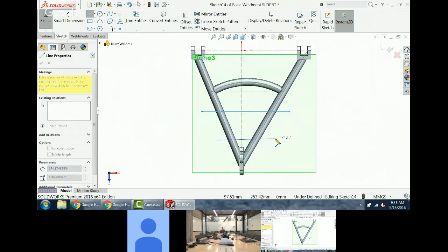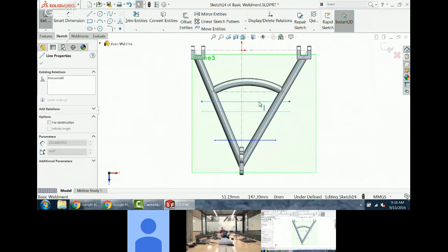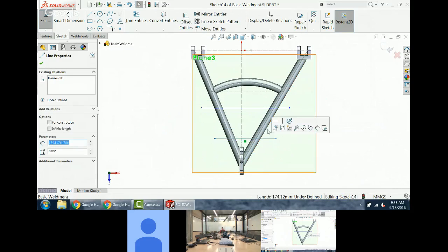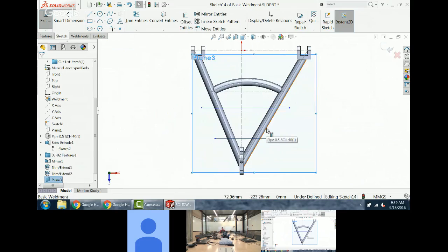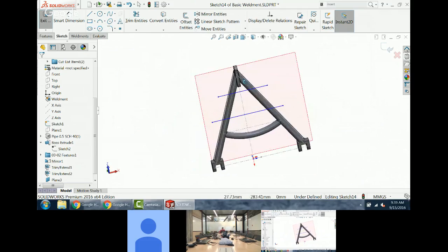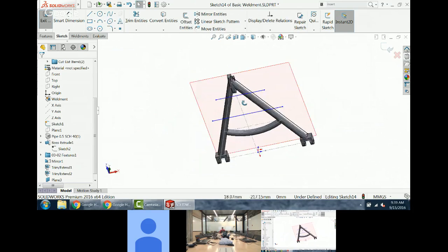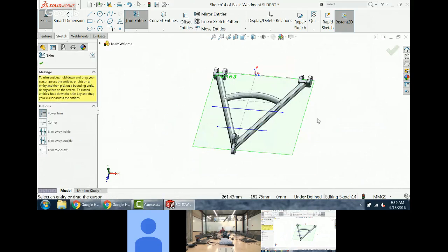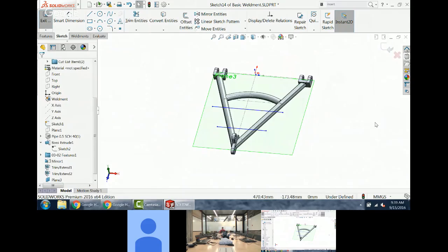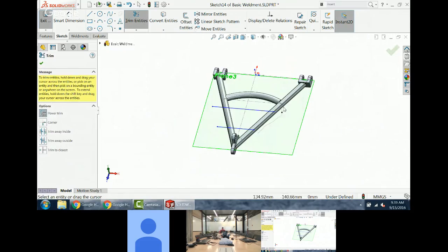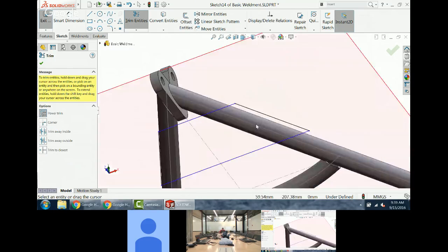What I'm going to do here is draw a couple of parallel lines, and then I'll grab the silhouette edge, which is the edge of that pipe as I'm looking straight down on my sketch plane. You see, there are those two lines that I just copied off the edge of the pipe. And I'll trim this up. Whoops. Going too fast. Let me try again. Trim. There we go. Just around so that I've got this trapezoid.